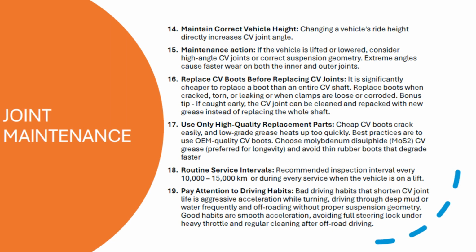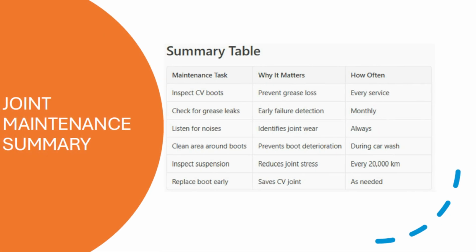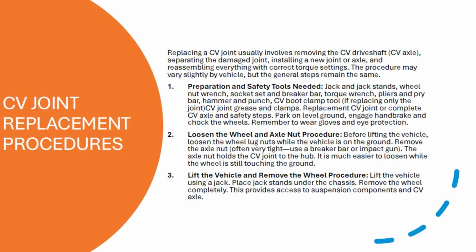Turning our attention to propshafts, we look at their role in connecting the transmission to the differential, ensuring the efficient transfer of power across the vehicle's length. Propshafts rely on center support bearings and universal joints to manage rotation and accommodate changes in the angle between drivetrain components during vehicle operation. Common propshaft issues often involve vibration or clunking sounds, which can stem from worn universal joints, failed center support bearings, or imbalances in the shaft assembly.